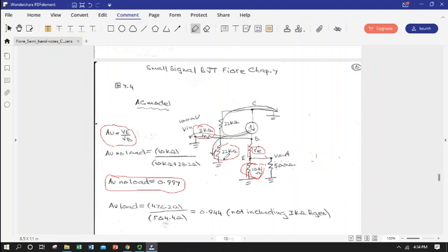So if we were to do that, we would be redefining these two numbers based on, in the case of V sub E, as the parallel combo of this 10K and this 500, and that turns out to be just shy of 500 and on the top, and then just shy of 500 plus 28 on the bottom, and so we get 0.944, so a little less, as expected.